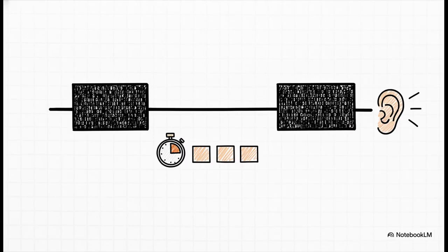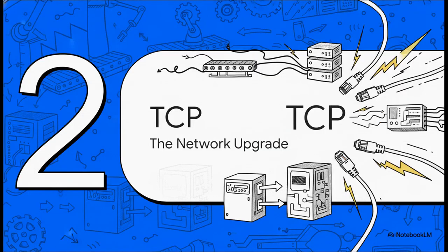So with all this data flying down one wire, how does a device know when one message has ended and the next one is about to begin? Modbus RTU uses this brilliantly simple method: timing. Devices are literally listening for a pause, a silent gap on the line that lasts for at least the time it would take to send 3.5 characters. When it hears that silence, it knows the last message is done and it can get ready for whatever's next. Pretty clever, right?